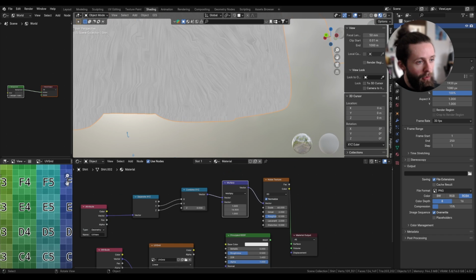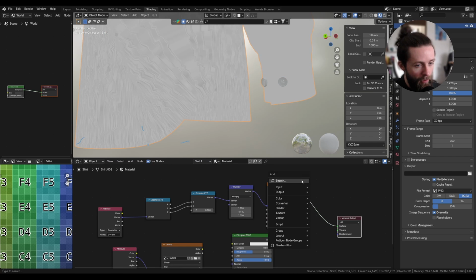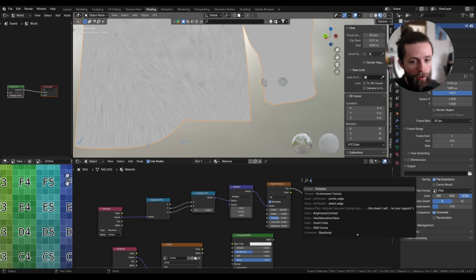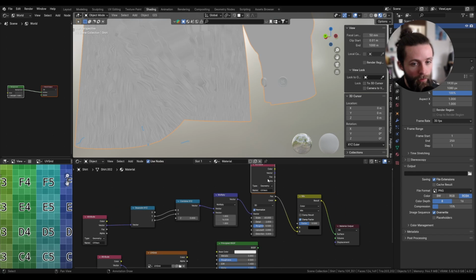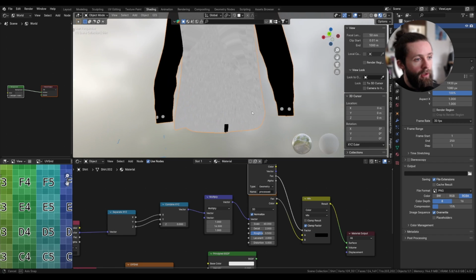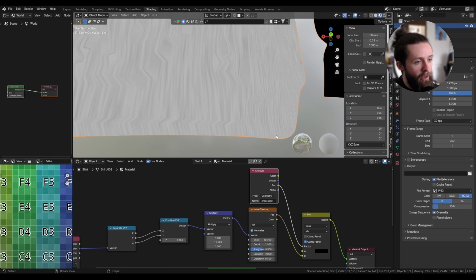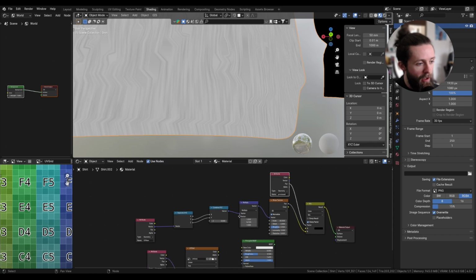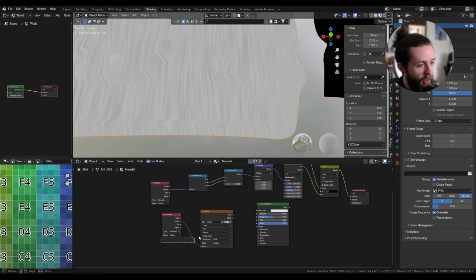And here you can really see that this custom UV map is following our hems, and this can look really nice. But of course this value doesn't exist for the geometry which we didn't process, so for that we can just use an attribute we stored at the beginning of everything to mix between two different colors, for example like this, and this attribute is just called processed. Now we get a black value everywhere where it doesn't exist. But also this value is only relevant on the side of our mesh near the hems, so you can blend between some value to make it disappear. And this is really easy.